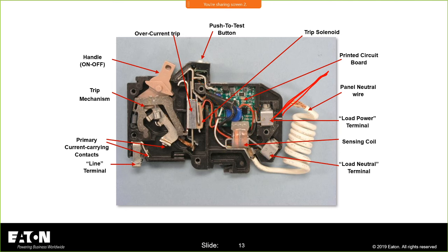This over here on this side is my thermal magnetic. So the brain is in here. There's the brain. You have to connect the pigtail. If you don't connect that pigtail, the brain doesn't get power. You just bought a very expensive thermal magnetic circuit breaker. Okay? That pigtail has to be connected. That powers the brain.